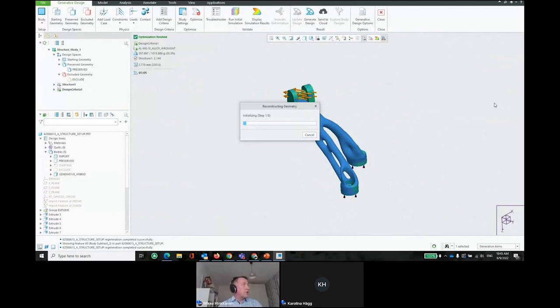What was the feature called? Freestyle maybe. Use a freestyle feature to map on top of it in order to create a C2 continuous surface set for you, which then basically gives you a total 3D body as a solid geometry.